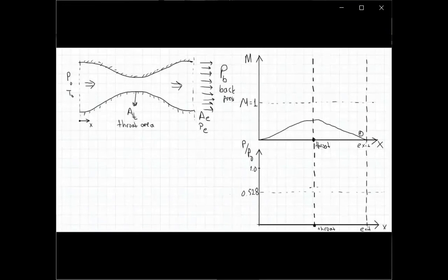So in that condition, corresponding to that condition, let's say, the pressure variation inside the converging diverging duct: as we get closer to the minimum area location, the throat location, we will reach a minimum pressure and then back again to a higher pressure level. Okay, so now we keep doing this experiment, extending it further.